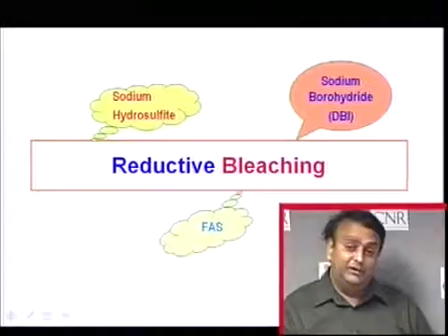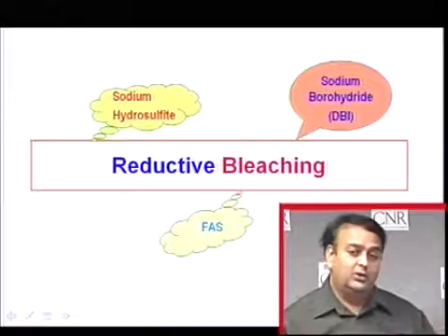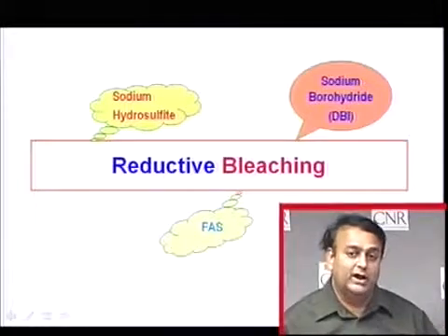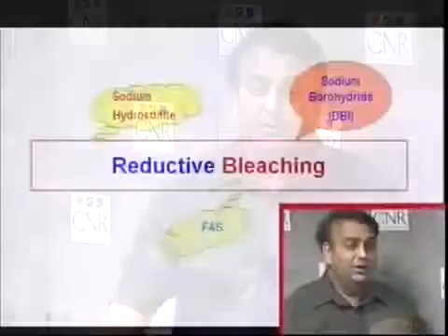That's the picture of the oxidative bleaching. We looked at chlorine-containing compounds, chlorine, chlorine dioxide, hypochlorite, and we also looked at peroxide, ozone, and then oxygen bleaching. Peroxide bleaching is the most common, widely used for bleaching recycled fiber. That's a good TCF bleaching chemical for this purpose. Now let me move on to reductive bleaching.